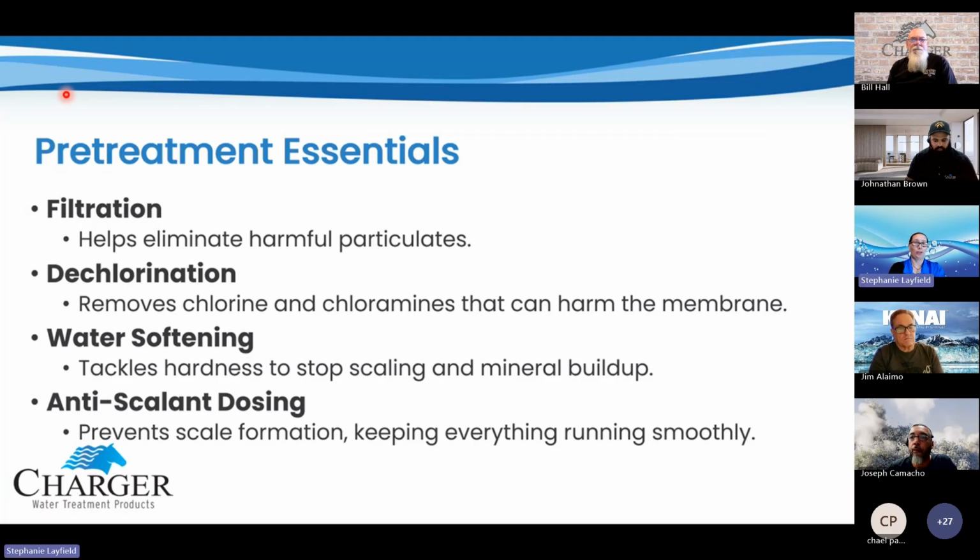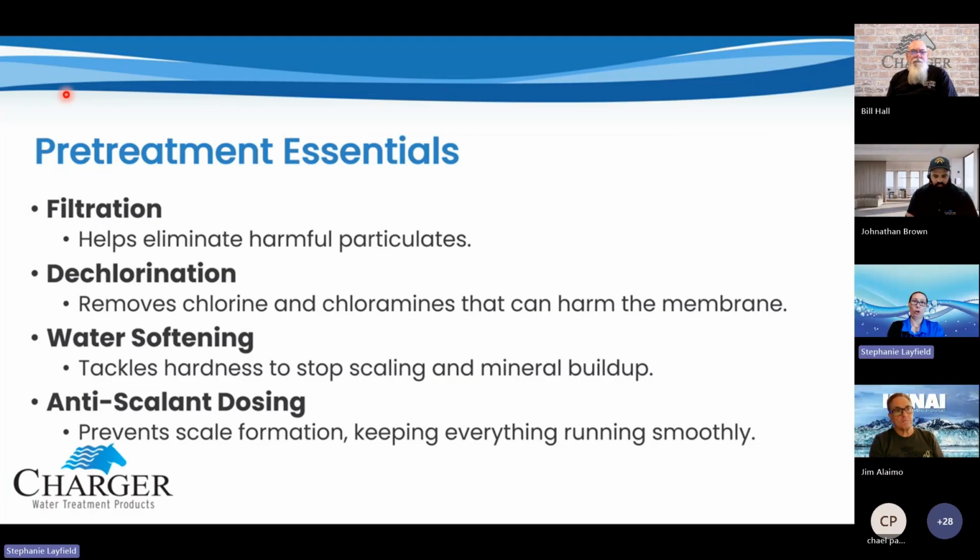The water softener, though, if you're looking at a large commercial application, that's a lot of water that you're putting through there. That's going to be a really high amount of salt, operational costs, and maintenance. So really consider the cost versus benefit of having an actual water softener versus dosing some type of anti-scalant in there. Usually on large applications.